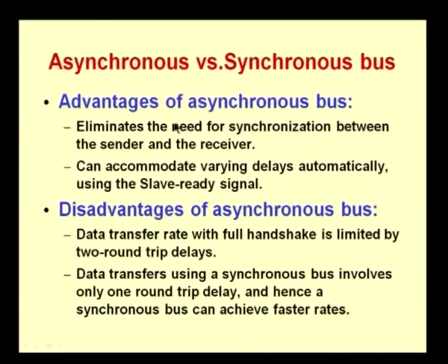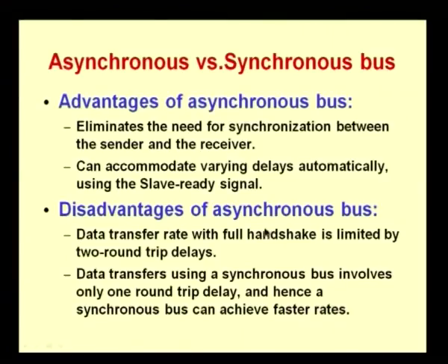So, if you do a quick comparison between the synchronous bus and the asynchronous bus, there are certain advantages of the asynchronous and certain disadvantages as well. What is the advantage of the asynchronous bus? It eliminates the need for synchronization between the sender and the receiver, that is, having a common clock and doing the synchronization with respect to that common clock. That is avoided when we go for an asynchronous bus. Second thing is you can easily accommodate varying delays using the slave ready signal.